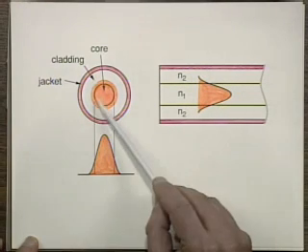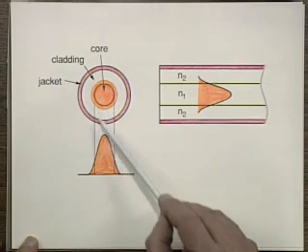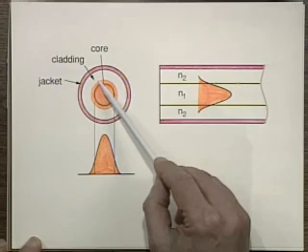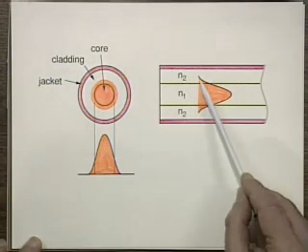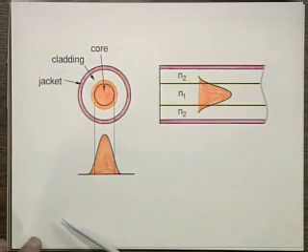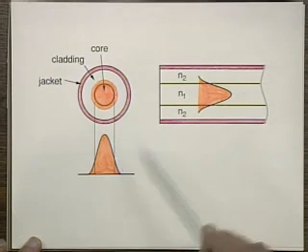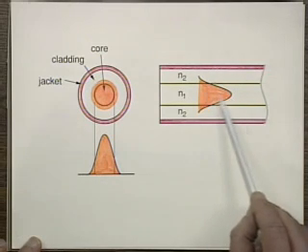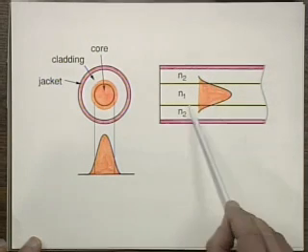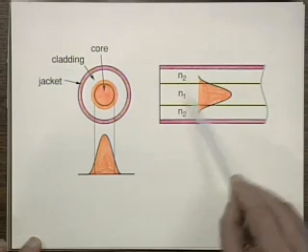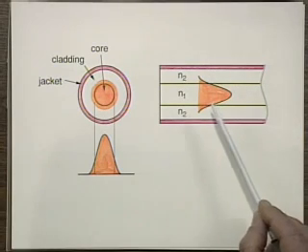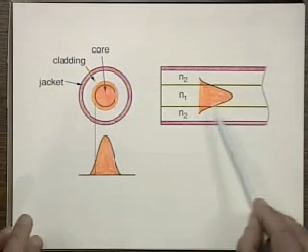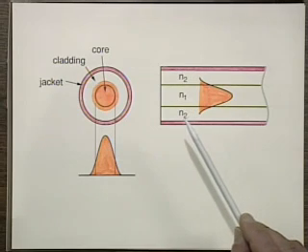So you can see this is the size of the core, but you see the orange, if you can see it as orange, it basically extends beyond the size of the core, and that's what we call single mode propagation. Okay, here's the field distribution, here's the size of the mode. So it extends a little bit into the cladding. Most of it goes into the core, part of it goes into the cladding, and propagates right down the fiber. I mean, this ray idea is fine for explanation, but when you do the proper calculation, that's what you get. You get this for the lowest order mode.